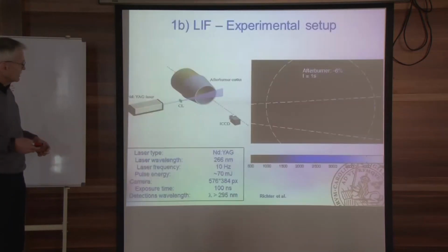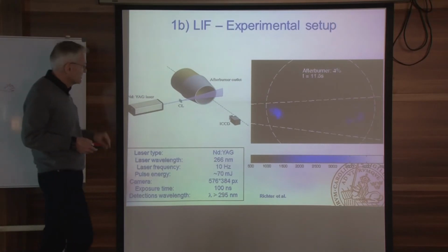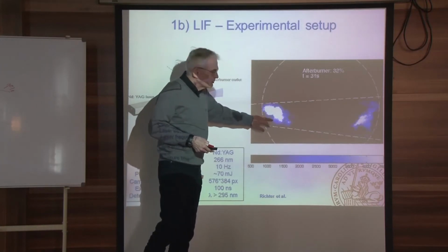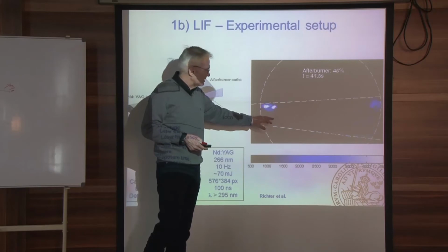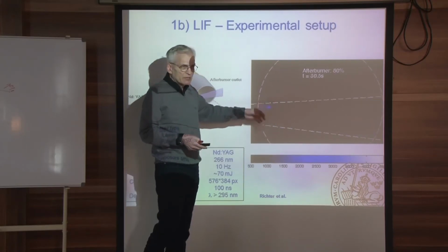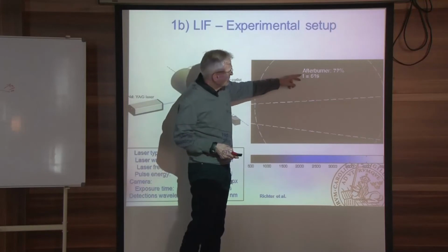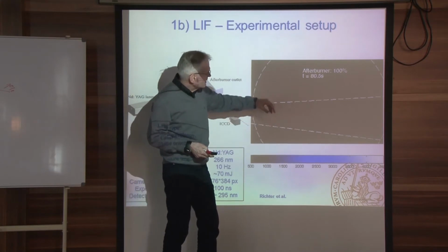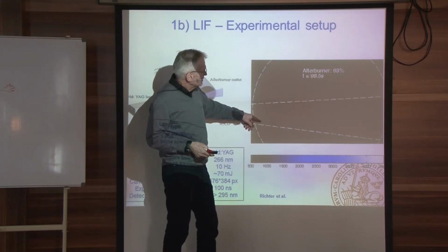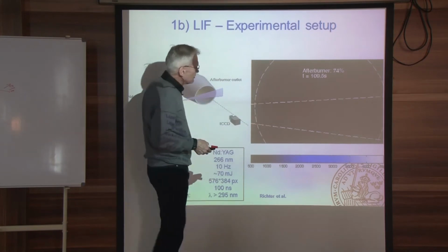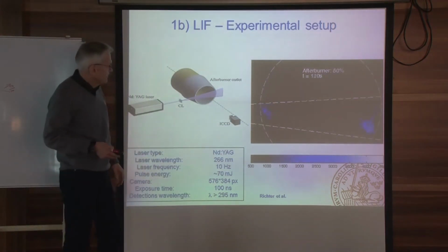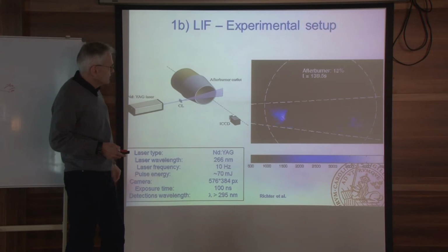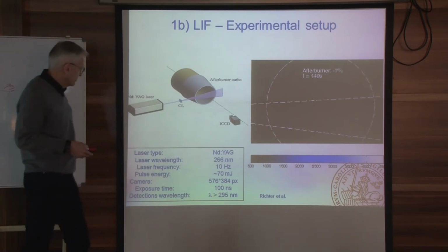And in this case, it worked out very nice, and I showed this yesterday, where they changed the degree of the afterburner, and you could see the emission from kerosene. So I can't quantify how much kerosene, but at least you could say that after 60% of the afterburner, you don't see any unburnt fuel. And then when it goes back again, it comes back around 60 something percent, 70, yeah. So they were very happy to see that they could get these results.